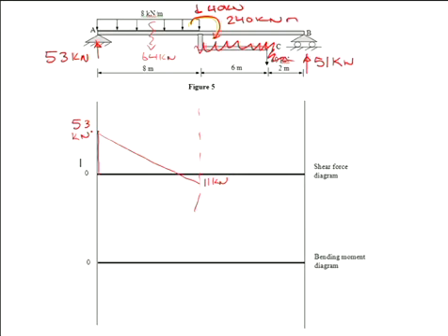Now we have a force of 11 here and we have a moment, no, the moment doesn't come into it. I do have a point load that brings us down 40. There's no load applied, so it brings us down a total of 40 to a value of 51 kilonewtons, and thank goodness that's the value of my reaction here. So all the forces in the y direction add up to 0, so I am happy. So I know I have got the right shear force diagram.